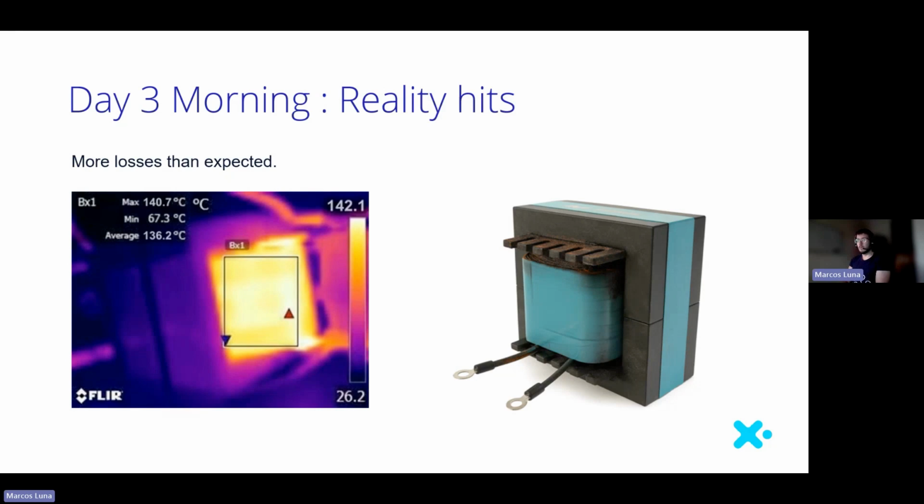The waveforms are clean, the system delivers the full power, the output voltage is correct, the output current is correct, but something happened. Something is starting to smell. Yeah, it's the coil former and also the tape of the inductor, which is starting to smell like melting.